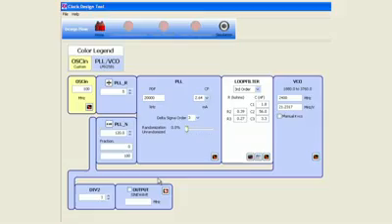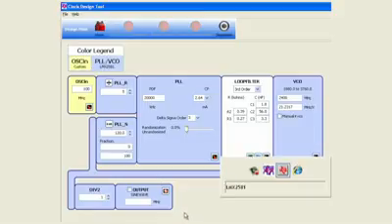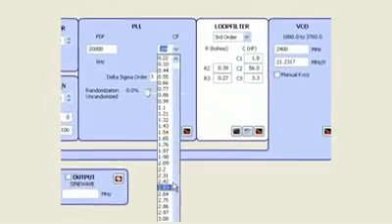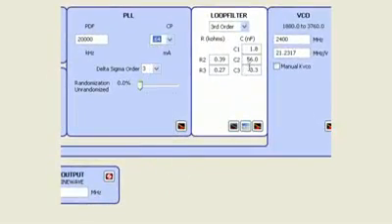Going into some of the other tools, we also have the clock design tool, which is useful for simulation and also design. So if we go over to this tool, we can set up our various frequencies. Here's 100 megahertz in, 20 megahertz phase detector, select your charge pump current gain. You can select your loop filter, and if you had whatever it is, you can type it in.